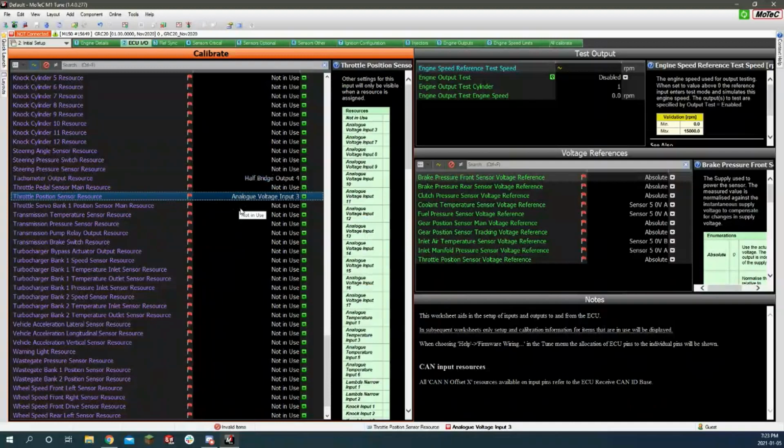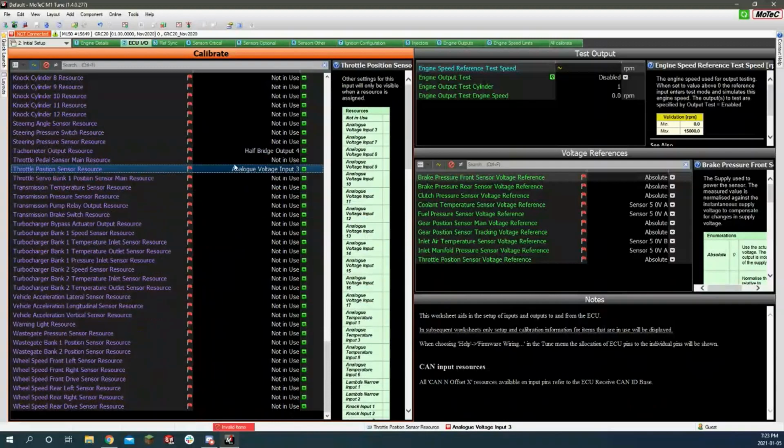build up fuel on the walls of the port of the engine. That's a bit of a technical thing that I won't get into too much detail on, but basically you need an extra spurt of fuel as you get on the throttle really fast. That's something carburetors do too, like more sports-oriented carburetors. They have a little device when you press on the throttle fast. It actually has a little pump that shoots extra fuel in. But of course, that's something that we control with the ECU.